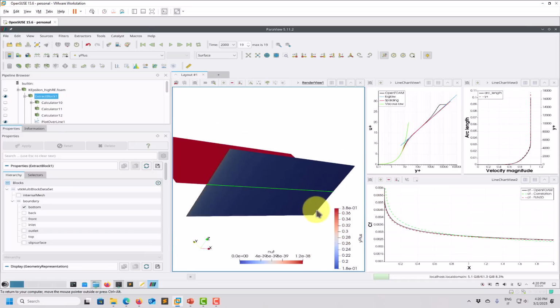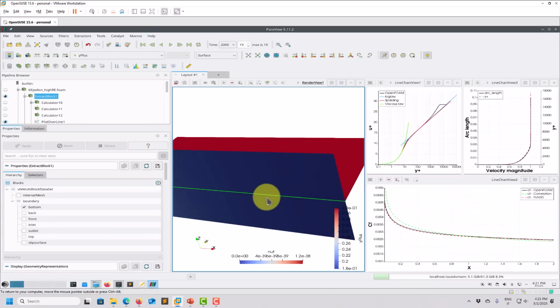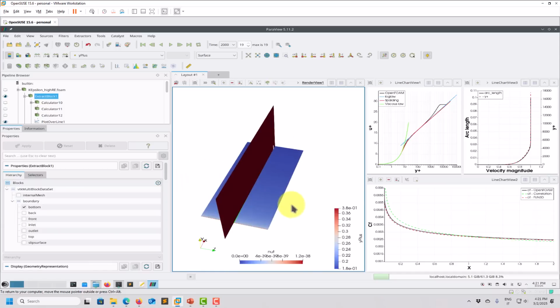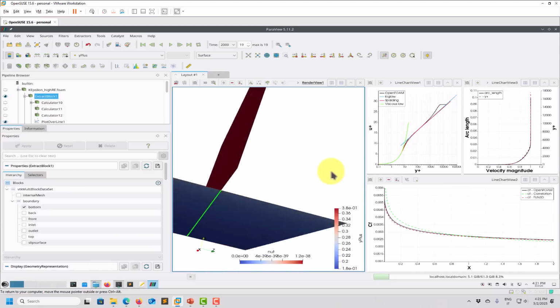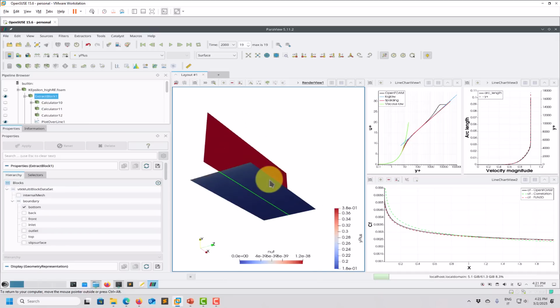But if you run a simulation and you get, I don't know, let's say a well resolving mesh, and then you get a maximum value of 100 that you know is outside that well resolving idea, and you get it here in the leading edge, that is a critical region. So better you should check what is happening. But if you get that peak in something here far, that is not a problem. Okay, so use some common sense. Or always plot your y plus at the walls and check where you have those critical regions, if there are critical regions. So in this case, nothing critical.